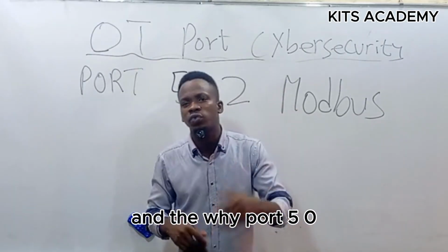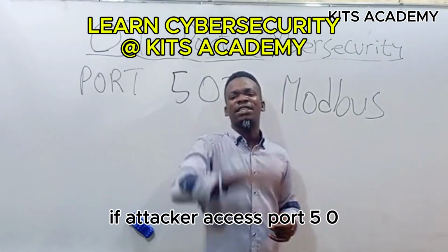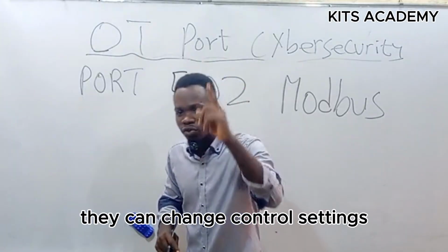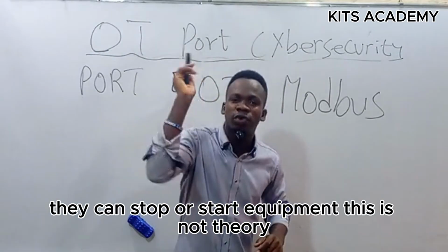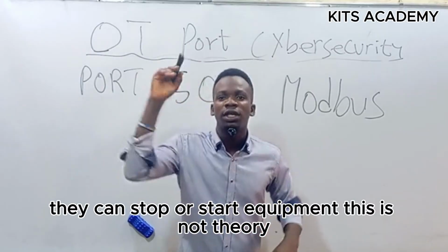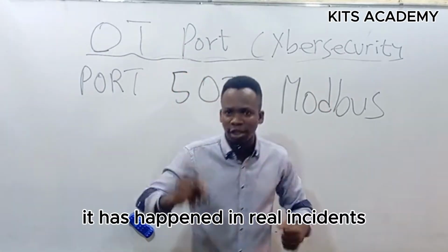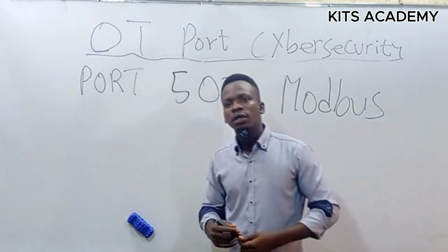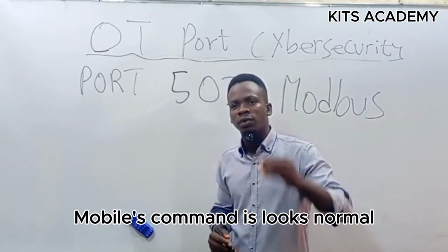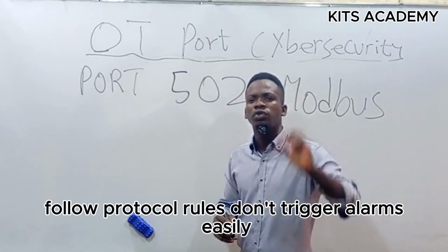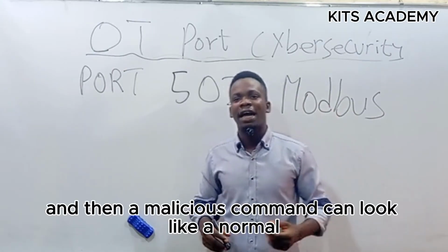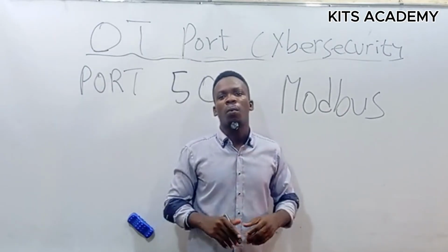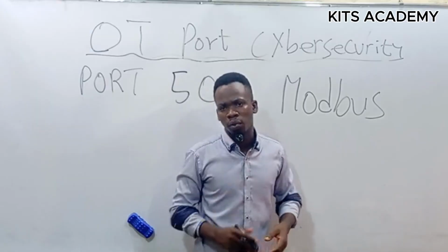And why is port 502 extremely dangerous if exposed? If an attacker accesses port 502, they can read process values, change control settings, and stop or start equipment. This is not theory, it has happened in real incidents. Now why are Modbus attacks hard to detect? A Modbus command looks normal, follows protocol rules, and doesn't trigger alarms easily, and a malicious command can look like a normal operator's action.